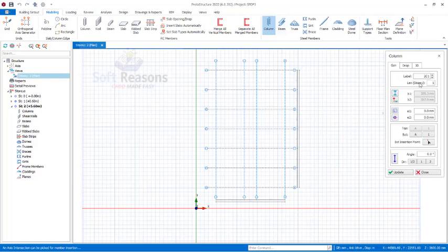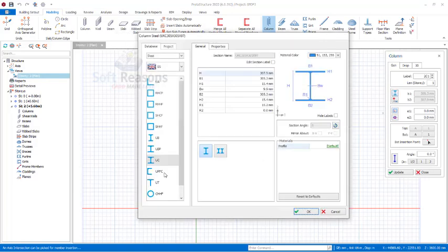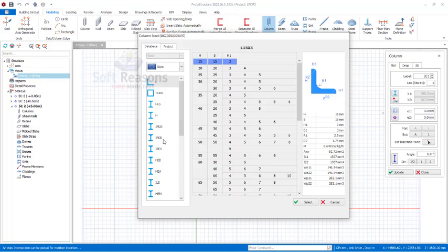All right, so in the steel column dialog, I will head over to the steel property, and then in this steel property sections manager dialog, I will go all the way to the database. This is BS. I'm not using BS, mind you, it was Euro code I'm using, so I will select Euro code as the database. All right, then I will head over to the IPE sections. So I will scroll down. I am looking for IPE sections.